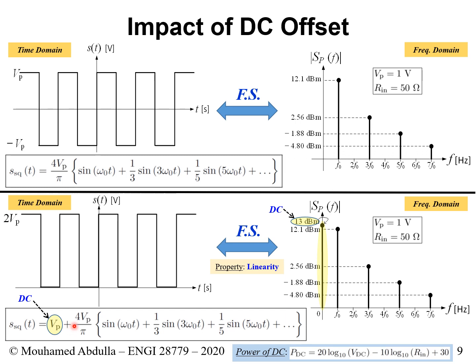The fifth way of knowing if you have a DC component, let's say for some reason somebody gave you the frequency response, or they display to you the frequency content of the signal, is to look at frequency 0. Do you have any spike? If at frequency 0 there is no spike, there is no DC component. If at frequency 0 there is a spike, well, there is a DC component. Right? So now I really showed you 5 ways of detecting DC.